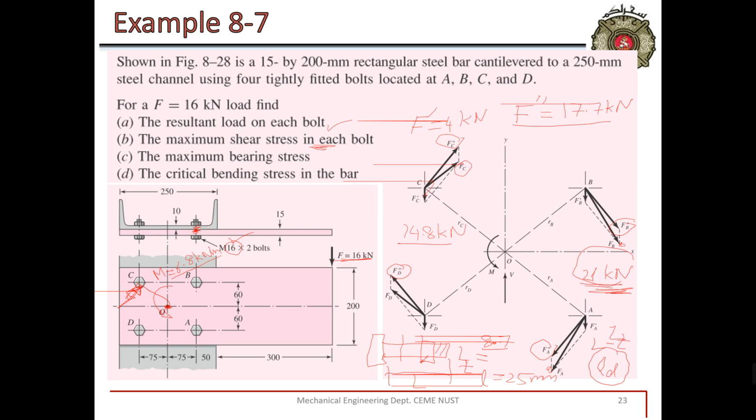And if the area at this point is threaded, then we have to use the value of AR from table 8.1. In this example, they calculated the length of the unthreaded portion, which comes out to be 8 mm. In other words, if this is the first plate, the shearing will be done here.